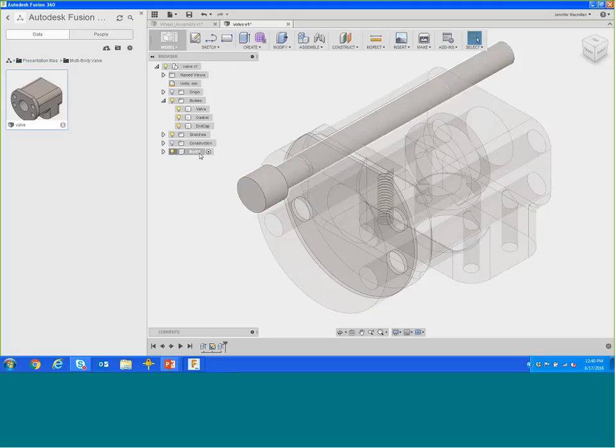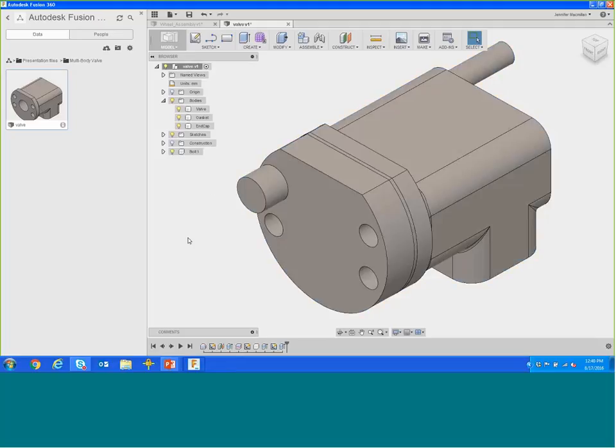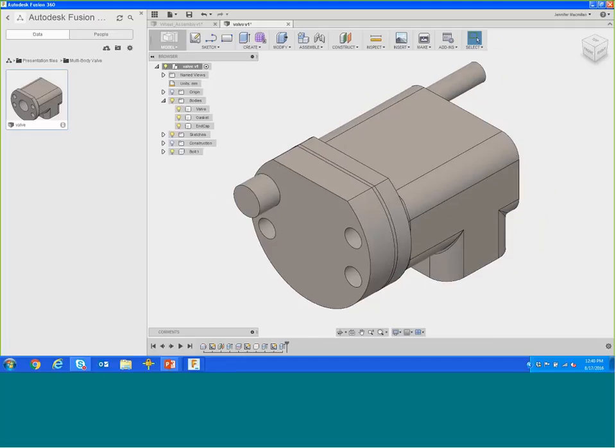To activate the top level assembly again, I just go up to Valve and select Activate Component, and you can see that everything now becomes blue. So I've now created that. Okay. In terms of next steps here, creating additional bolts, joints, all that type of thing, you definitely have to go through and do all that.